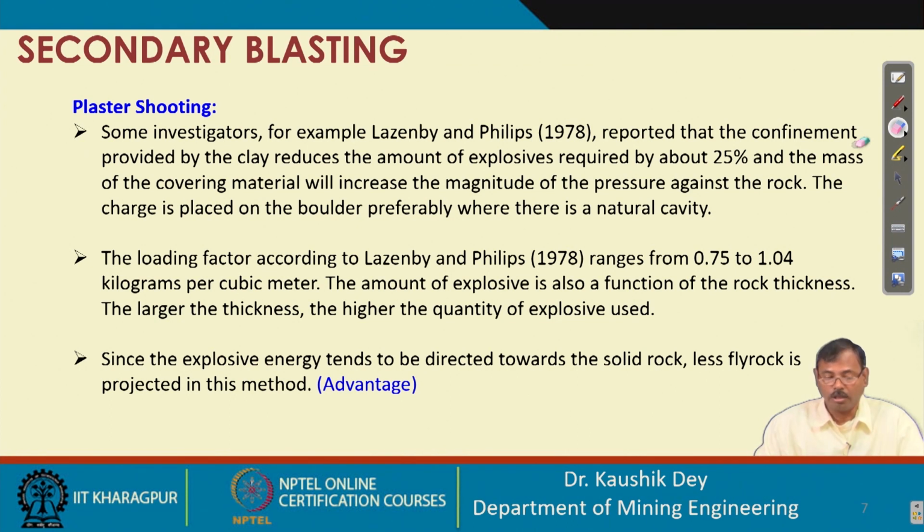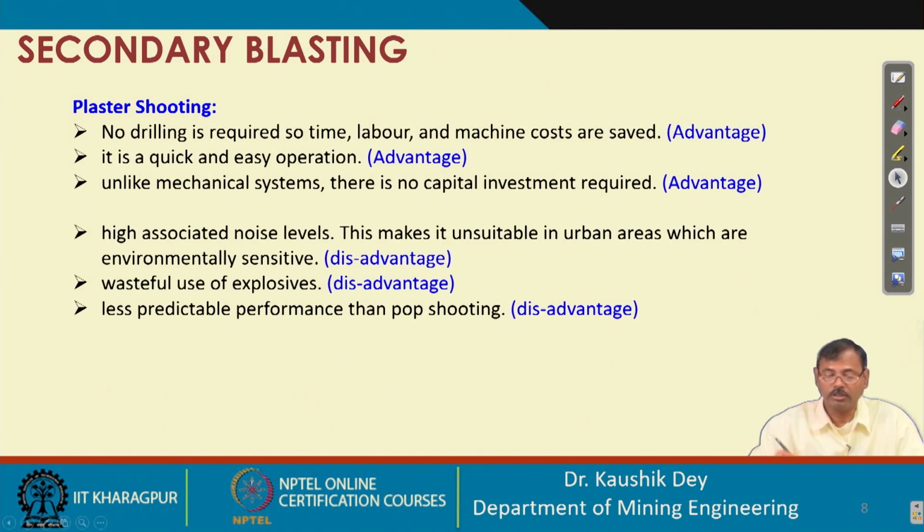But the difference is that we do not need any drilling, and the generation of fly rock is not very significant, as the explosive is in the top part and the boulder is in the bottom part. So the chances of fly rock are not very high, but the detonation of the explosive in the air medium generates huge noise. This is a difficulty.